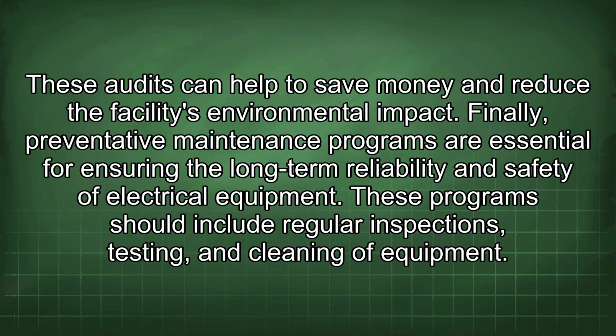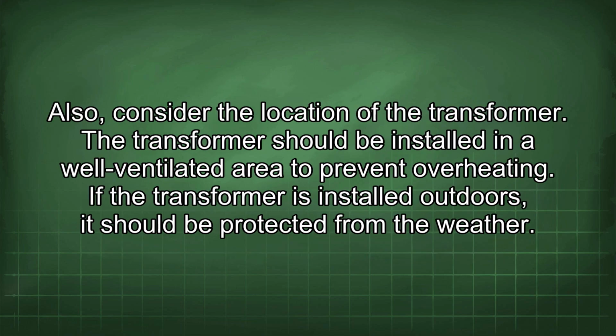Finally, preventative maintenance programs are essential for ensuring the long-term reliability and safety of electrical equipment. These programs should include regular inspections, testing, and cleaning of equipment. Also, consider the location of the transformer. The transformer should be installed in a well-ventilated area to prevent overheating.